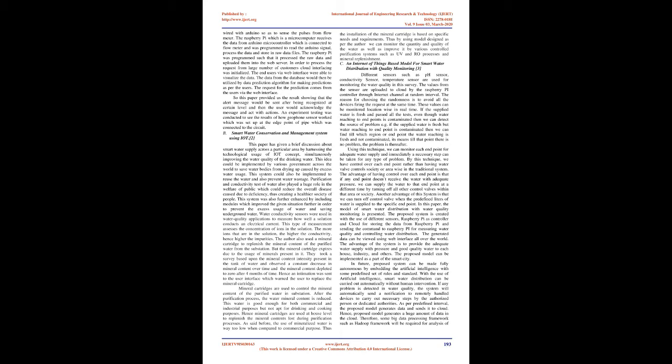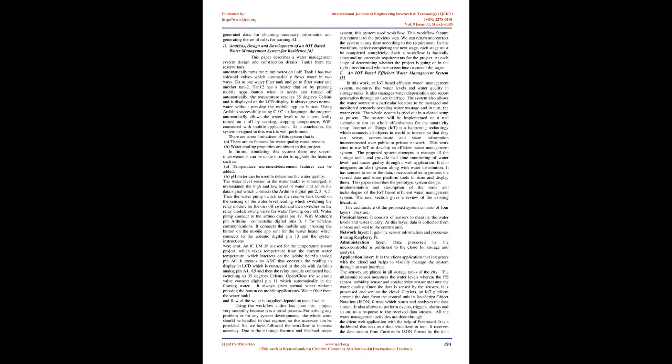Tank 2 has a heater that is turned on by pressing a button in the mobile app when needed, and turned off automatically when the temperature reaches 35 degrees Celsius, which is displayed on the LCD display. It always gives normal water without pressing the mobile app button. Using Arduino, programmed successfully in C/C++, the system automatically turns on and off based on water level sensing and temperature, with Wi-Fi connected to mobile applications. As a conclusion, the system designed in this work performs well.